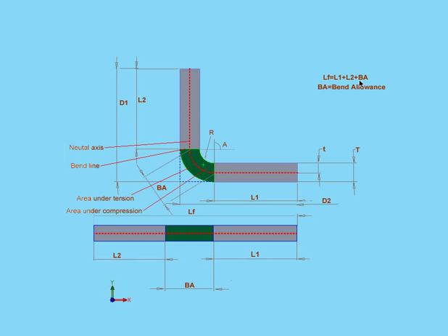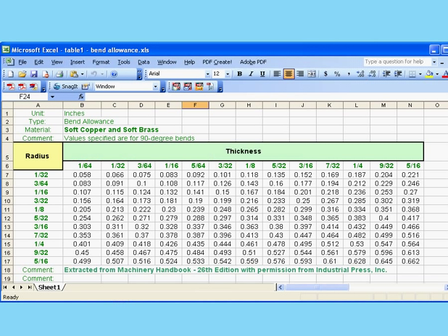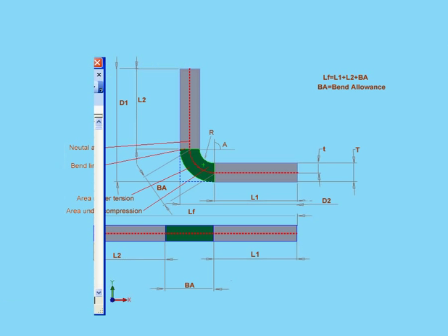The value of the bend allowance that comes from sheet metal suppliers and manufacturers, as well as engineering textbooks, is provided in bend tables, and a bend table looks pretty much like what I've got on my screen now. This is an Excel spreadsheet. The bend table approach is probably the most accurate approach for calculating bend allowance. You can input your data manually into a matrix of the bend angle and bend radius. If you're not sure of the bend allowance value, you can run some tests.